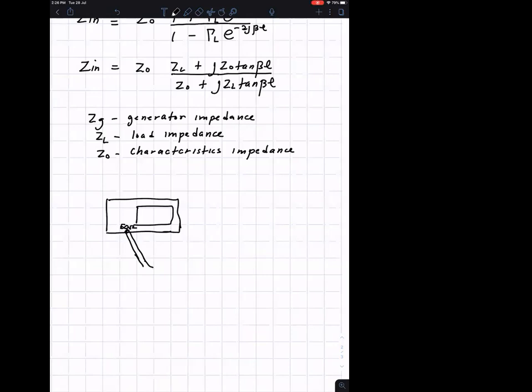If you connect a cable here, this cable also must have 50 ohms. All must be 50 ohms. So any device that you connect to the cable also must have input impedance, output impedance 50 ohms. They all are matched. If that is the case, then there will be no reflection.